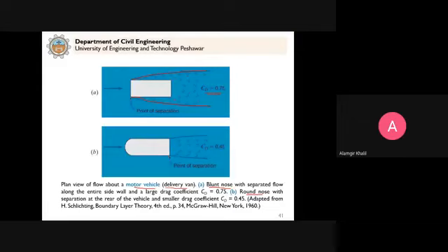You see the size of the wake is reduced. So what is the effect? That the drag coefficient is 0.45. So that's why this vehicle will travel faster as compared to this vehicle for the same power. This is what we studied earlier in the previous chapter, streamlining of the cars. And we studied a graph there over the years. We are streamlining the shape to reduce the drag forces on the cars so that the mile coverage is increased.